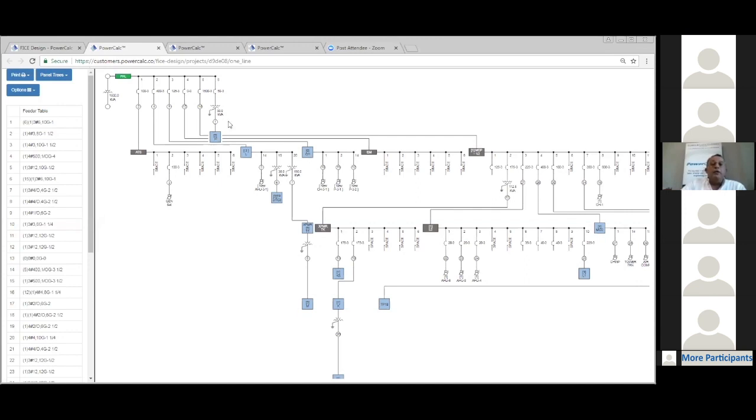To initiate the fault current, I would like to mention one more thing here. The electrical service is from FPL, Florida Power and Light, the power company. It was estimated at a 1500 kVA transformer. These are values that you need to get from the power supplier: the size of the transformer, or the available fault current at the primary side or the secondary side of the transformer provided by that particular power company.